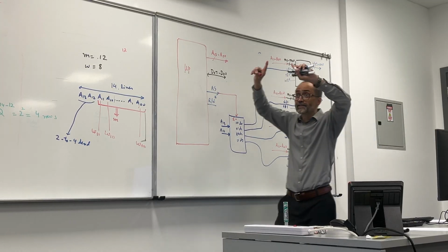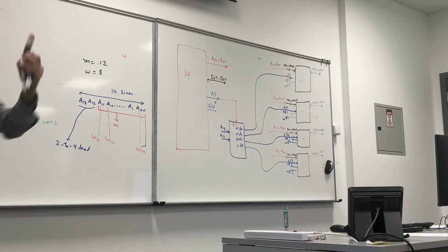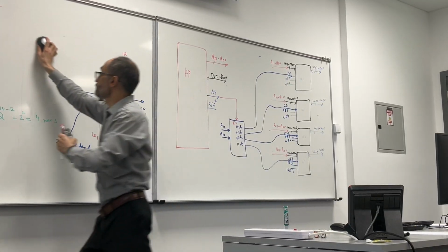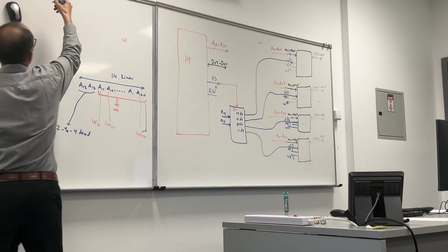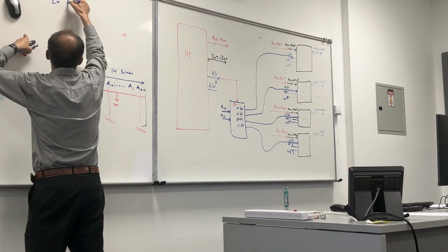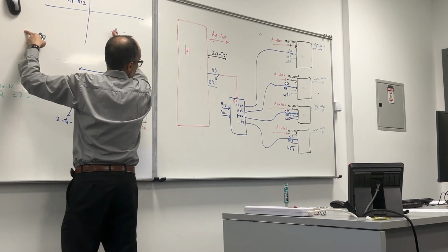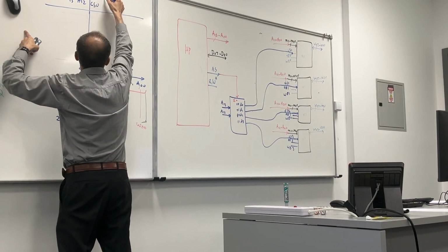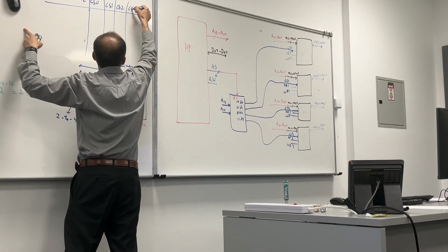Please remember, this is now my digital system. Now if you look at the input to the decoder, we have enable on the decoder side, and then we have A13, then we have A12, and the output is what? The output D0, which is actually chip select 0, then we have chip select 1, then chip select 2, then chip select 3.